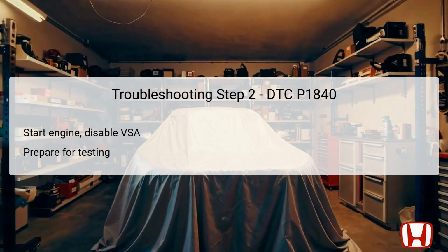After disabling the VSA, the technician prepares to conduct a confirmation procedure, whereby accurate readings from the CVT speed sensor will need to be obtained. This prepares the technician to verify whether the sensor is functioning correctly, ultimately targeting the root cause of the DTC P1840. This step directly influences the findings in subsequent troubleshooting actions.